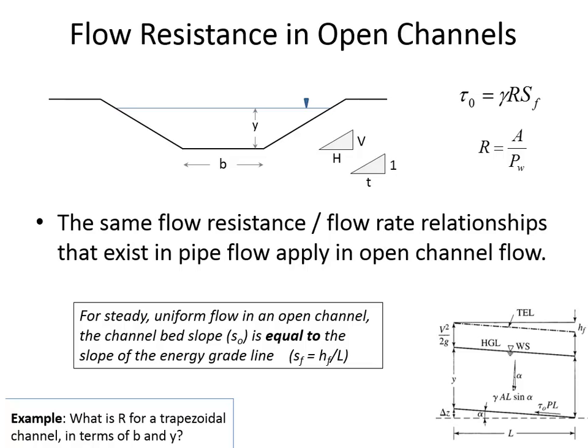Okay, so obviously you can break it up into pieces, right? You'll have this rectangular piece that is B times Y, and then you've got two triangles, one on either side of the trapezoid. So if you put them together, that's just another rectangle. So it's going to be B times Y plus Y times TY. In other words, that is BY plus TY squared. That is the area.